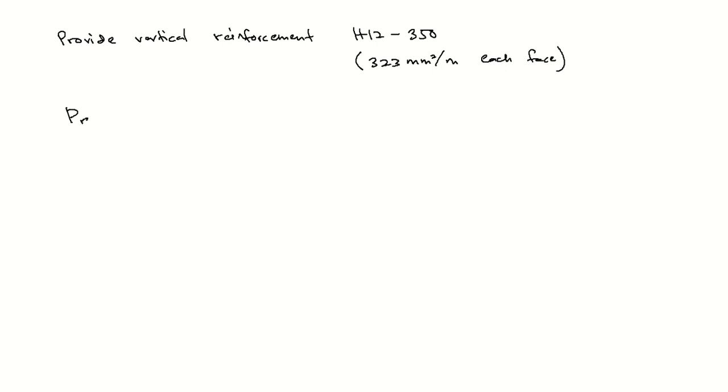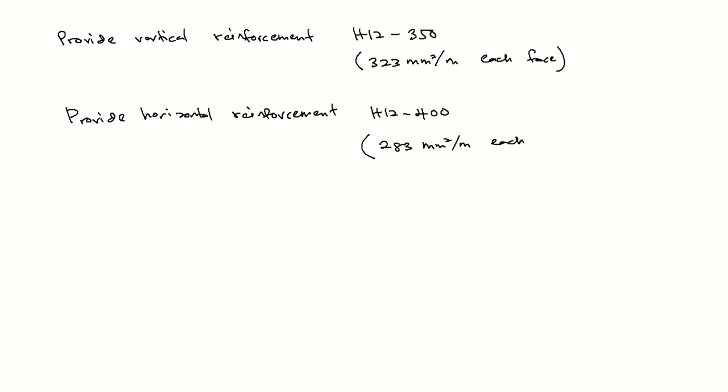And also we can provide horizontal reinforcement of H12 at 400, which is 283. So basically we have checked the top story and we can extend the reinforcement.